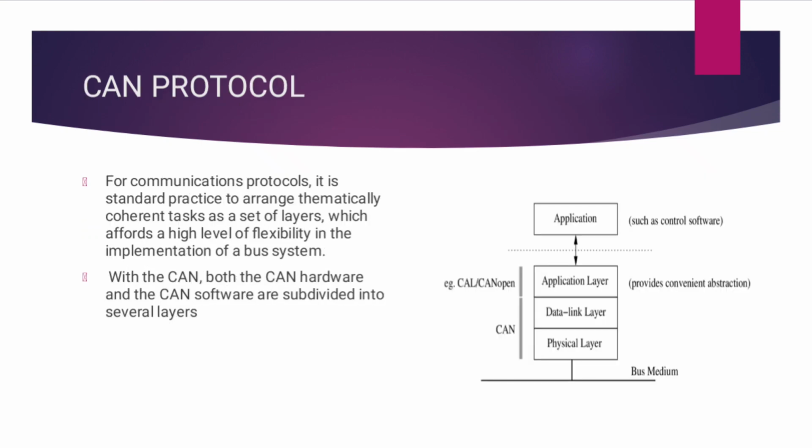CAN protocol. For communications protocols, it is standard practice to arrange thematically coherent tasks as a set of layers, which offers a high level of flexibility in the implementation of a bus system. With the CAN, both the CAN hardware and CAN software are subdivided into several layers.